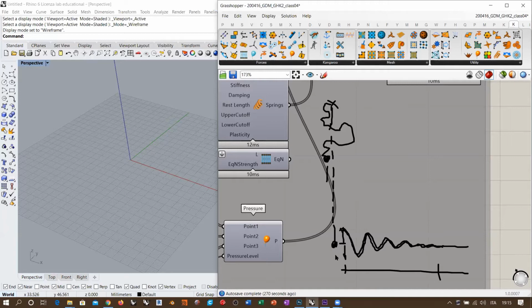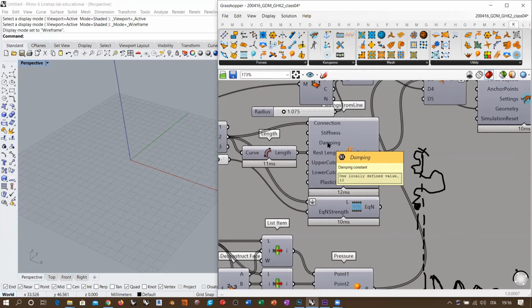It will stretch a little more, and then because of its elastic force, it will go back and contract a little, and then extend a little, contract a little, and so on. It starts to oscillate around the equilibrium position. This oscillation will end sooner or later. And this time here that the spring takes when it reaches more or less the equilibrium status, before it stops in that equilibrium status, depends on the damping constant. So this is the meaning of this value here.